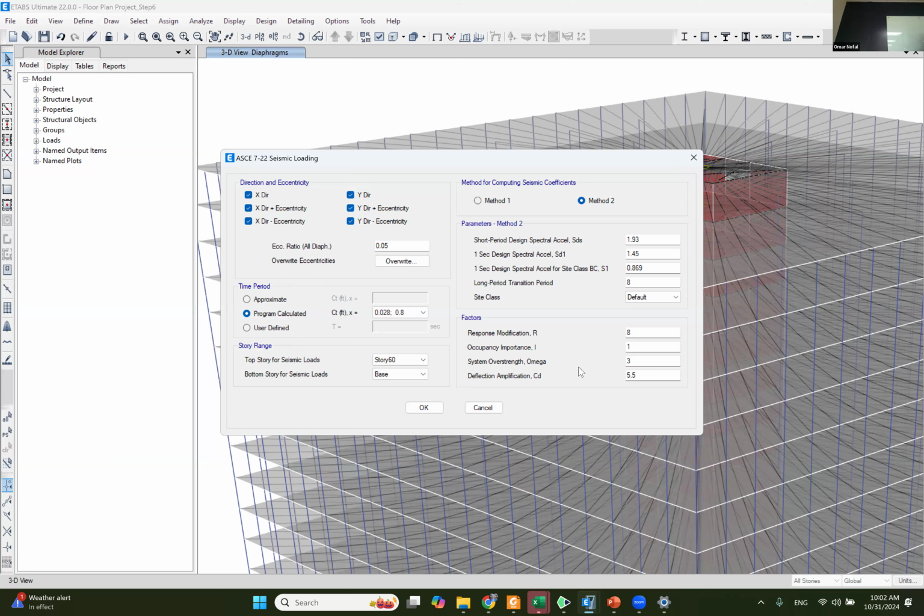Okay, so do you guys remember when we said we are converting the earthquake to one base shear hitting the building? You ask me, where is this base shear hitting the building? It's hitting the building at the center of mass. So that's the point of application, okay? But you'll tell me, okay, it's gonna hit the building at the center of mass, but this is gonna drag us into a different conversation. We don't want to spend a lot of time on it.